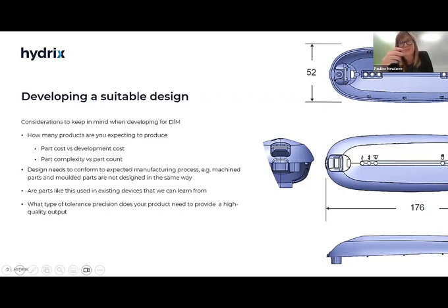Again, there are some general bandwidths for different sizes of parts and different manufacturing processes that can be utilized as a good starting point. And then I think it's that interaction with the manufacturer where you go in and have a discussion about where there are some critical things where those tolerances create extra work for them, and whether there are any options of trying to widen the tolerances in those areas.